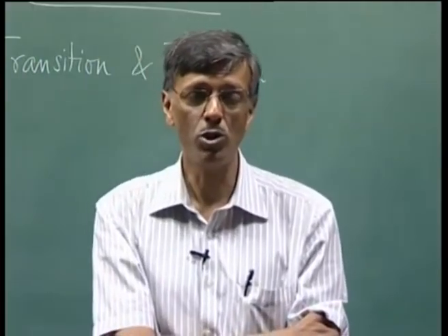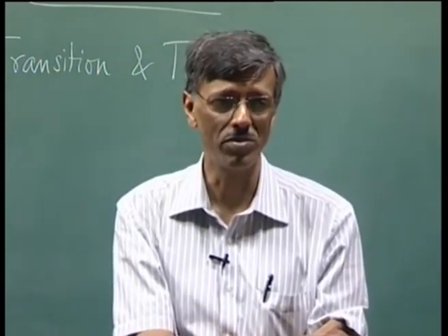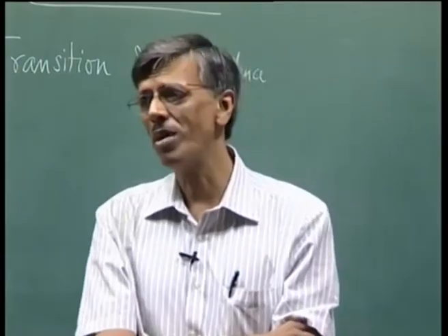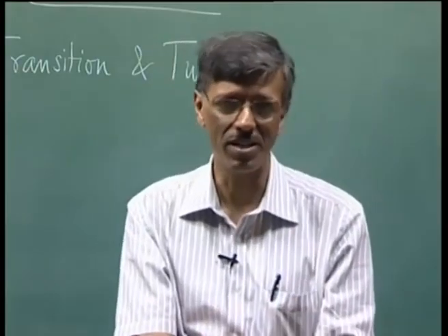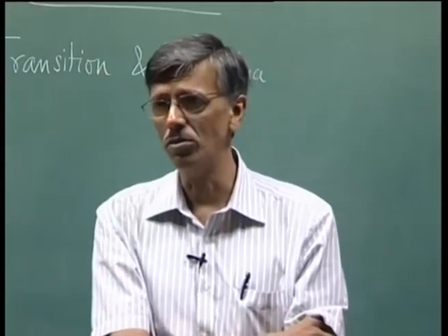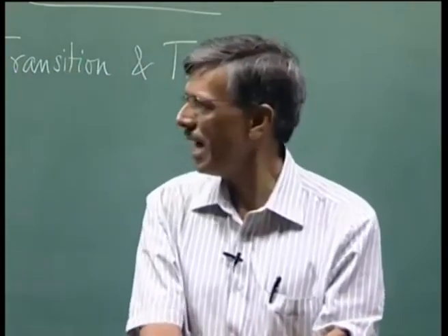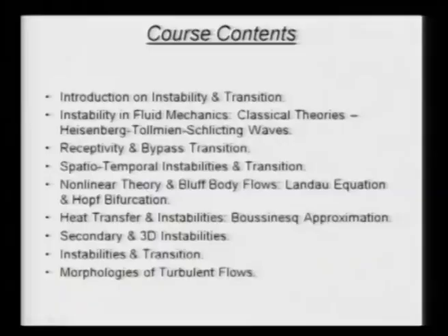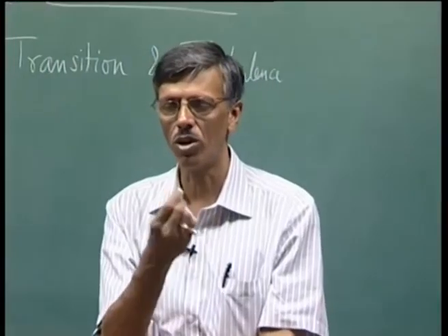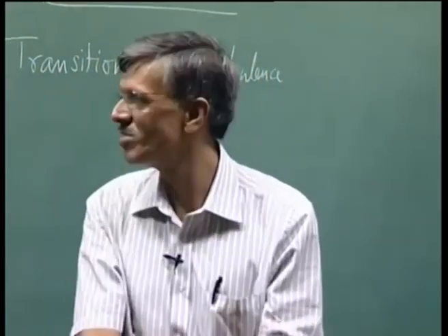found out. Schubauer and Skramstad noted that not all disturbances produce waves. They could produce waves only when they vibrated a ribbon inside the boundary layer. They found out that if you try to excite the flow with acoustic noise, it does not create waves. And that is the subject that we talk about in what we call receptivity, that the flow is receptive to a certain class of disturbances. Not all disturbances can give you instability waves.